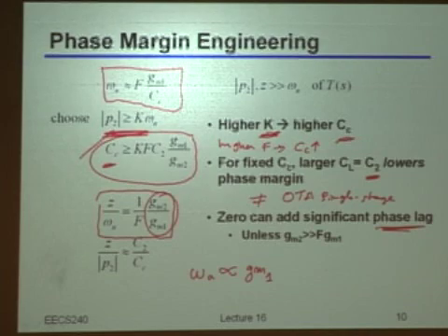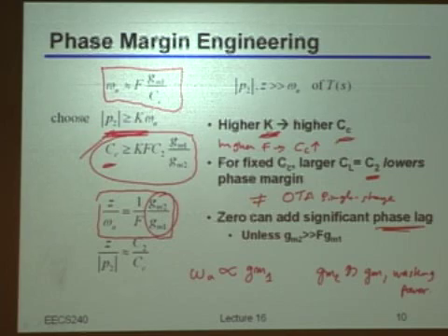GM2 is the second stage GM. It's just power that you are spending, most probably, just to place the zero far away. If you go for GM2 much larger than GM1, you're just wasting power. It's something that you wouldn't like, because you're not employing power for good settling. And so that's almost nothing that you can do. The position between the zero and the second pole is decided by basically this ratio of capacitances.